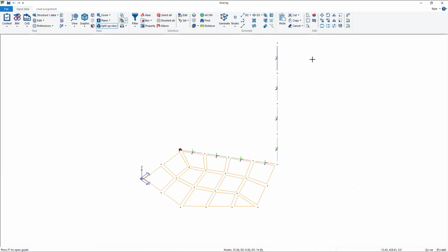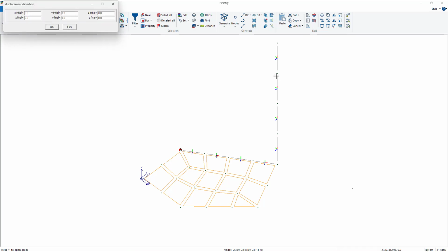Last important comments about modeling and editing what I modeled: I think it's stretch box, which allows me to move a node and all elements connected to it. I need to select the node that I want to move, and let's say I want to move it on X by 50.